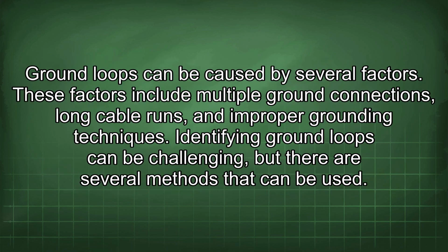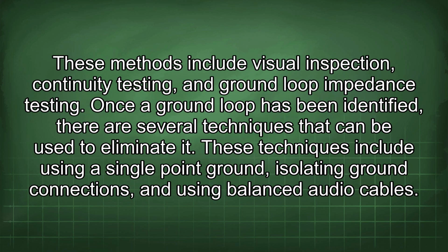Ground loops can be caused by several factors. These factors include multiple ground connections, long cable runs, and improper grounding techniques. Identifying ground loops can be challenging, but there are several methods that can be used. These methods include visual inspection, continuity testing, and ground loop impedance testing.